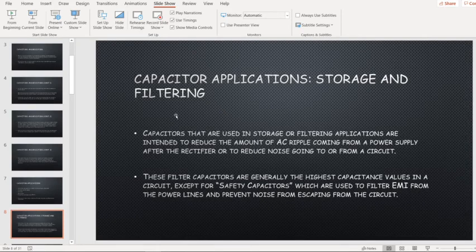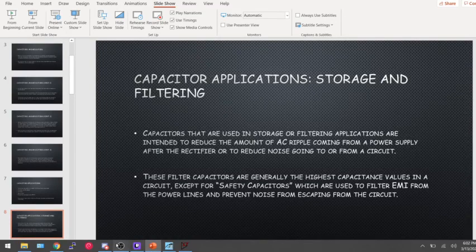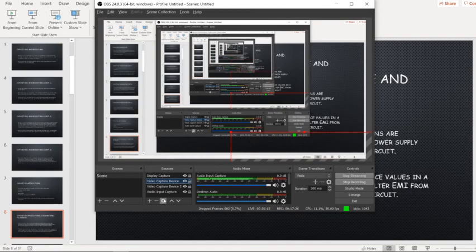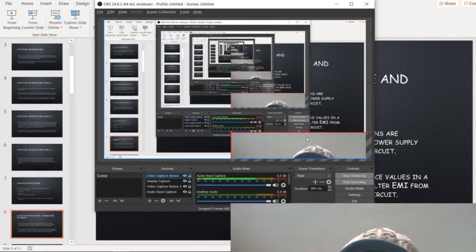So essentially what happens is that when you have a capacitor, it's not going to completely block your DC current, because it's got a high resistance in the dielectric, but it's not an open circuit. And as a result, there is a tiny, tiny, tiny amount of current that flows through it. So when we're looking at old capacitors, let me show you this one. I think this is the, nope, yep, that's it.